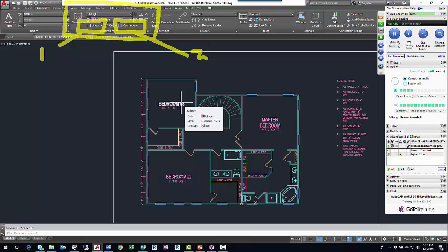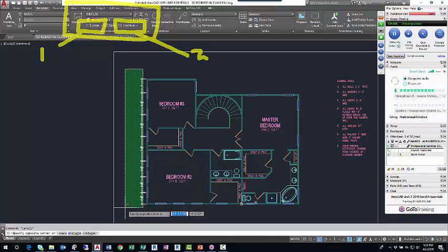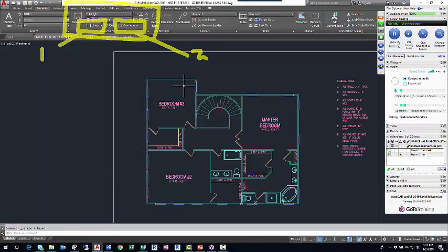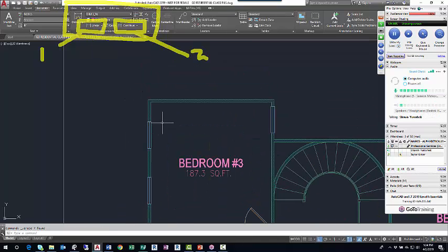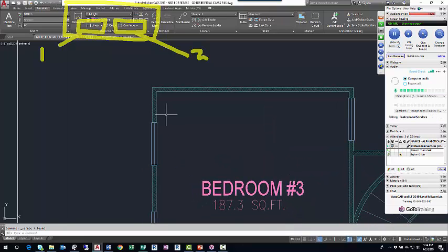Can you go explain that again real quick? Yeah, I'll explain it slow. Let me get rid of this stuff. Just how to place the dimensions, right? Yeah, the Linear and a Continue. Mm-hmm. So I like this. Honestly, you could use Linear for all your dimensions, but it's more work than you should have to do.